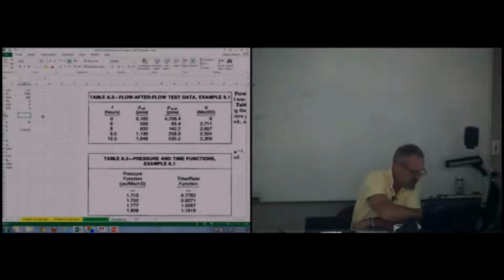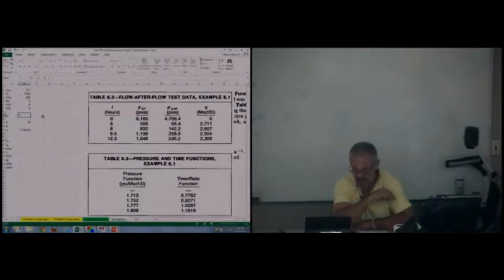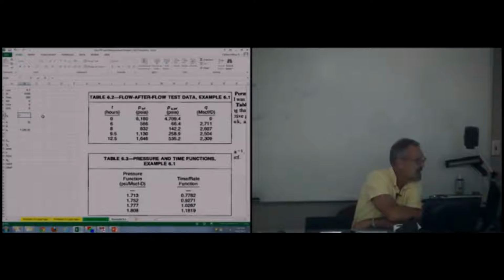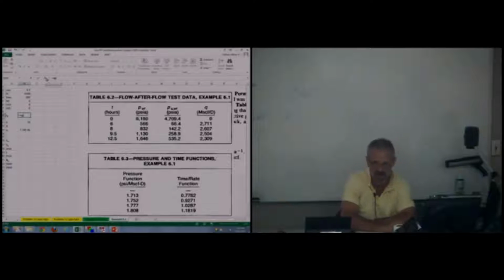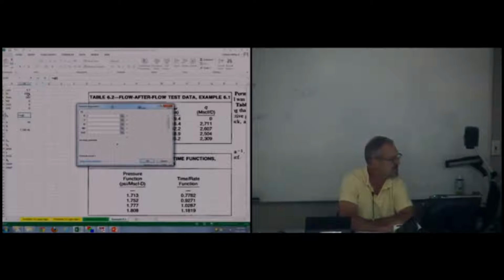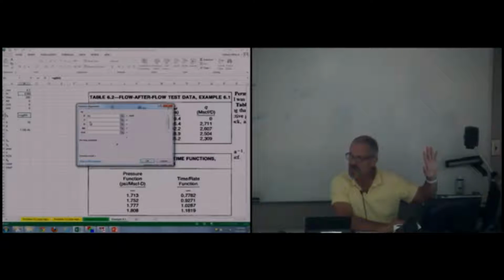Equals, very good. What's the next keystroke going to be? C. And there it is, gas compressibility. And then if I click my f of x box up here, it will invoke the dialog window. Pressure. Already thinking ahead, knowing that all my fluid property functions have the same variables in the same order, all I have to do is change the spelling if I want a different one.